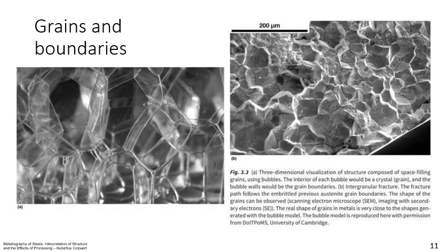Now, the dendrites don't survive the steel making and pipe making process. And as we've talked about steel making and pipe making, there's many steps that involve heating and deformation of the steel. And that extensive deformation adds hot work and makes it energetically favorable to break down those old grains, the dendrites, and form new grains with more energetically favorable shapes and relationships to one another.